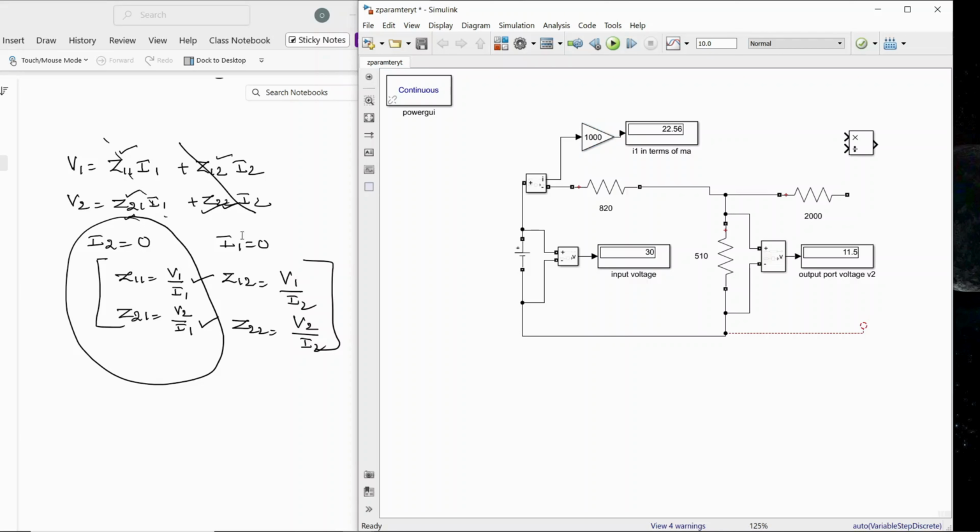So now I want the block of numerator should be V1. Where is V1? Here it is V1. Okay. So now just use one button, drag it and keep it there at V1. So if you have any confusion, you can move it out. So this is V1. Okay, and you require V1 by I1. So in the denominator I require I1. So no need to write down the 1000, right?